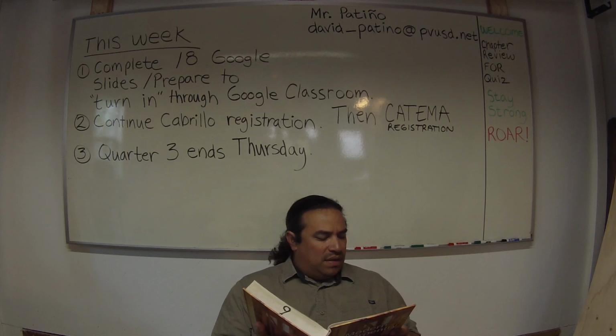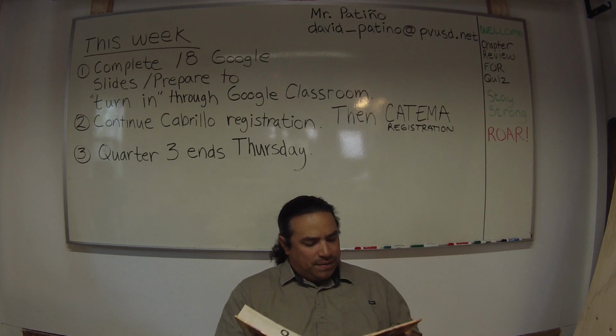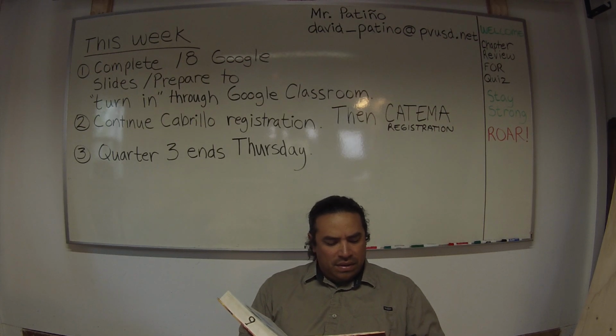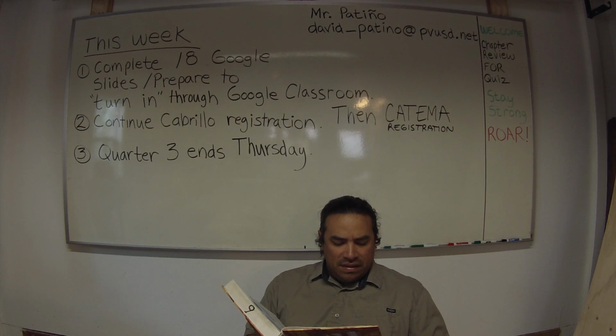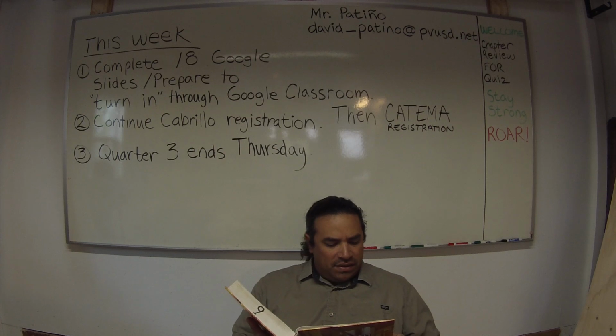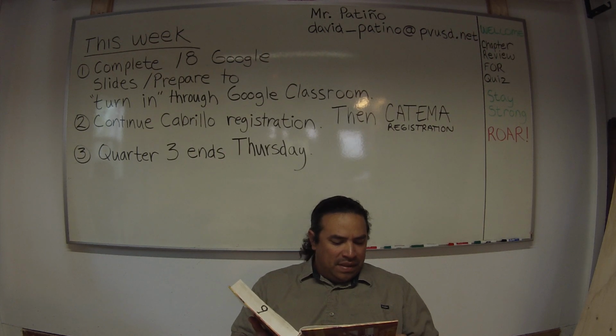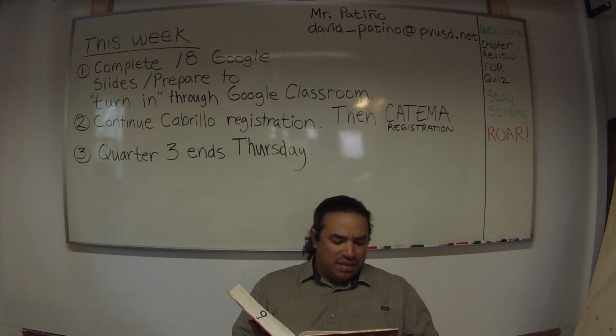Tiny strands of cellulose make up the cell walls. The cells are held together with a natural cement called lignin. This cellular structure makes it possible to drive nails and screws into the wood. It also accounts for the light weight, low heat transmission, and sound absorption qualities of the wood.